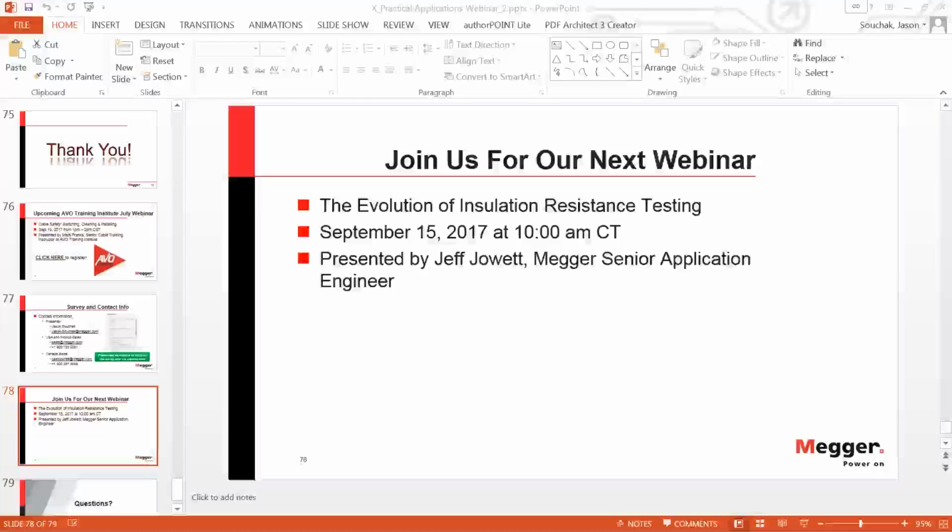All right, next question is for Jason. What is the standard value of tan delta? Okay, there's no specific standard value. That's why we have the IEEE charts, so that you can go and reference them. I'll tell you though that typically your magnitude of them is going to be 1 to 2 or 3 times 10 to the -3rd radian.